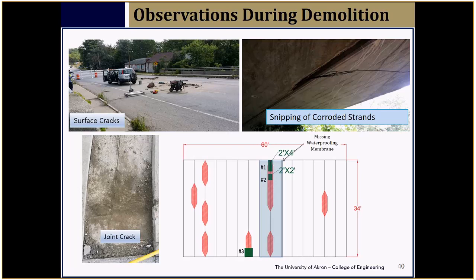These box beams are precast beams, so they can easily control the amount of fiber they use in the bridges, in the beams. So if we add some fiber in there, this type of corrosion damage is likely to be resisted. So instead of 30 years, we may get 50 years service life or even 60 years.